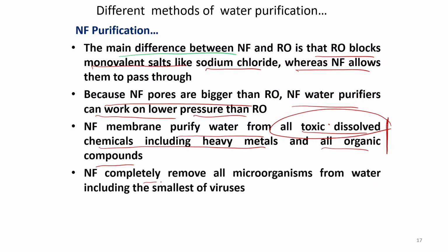It also completely removes all microorganisms, because their size is much larger than the nanofilter pore, including the smallest viruses. Bacteria it will anyway remove, but it can remove even the smallest viruses from water. So, this membrane is very important. It also works at lower pressure than the RO filter.